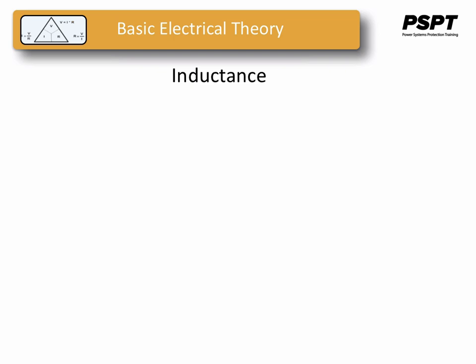Whereas an electric field flux between two conductors allows for an accumulation of free electron charge within those conductors, a magnetic field flux allows for certain inertia to accumulate in the flow of electrons through the conductor producing the field. Inductors are components designed to take advantage of this phenomenon by shaping the length of the conductive wire in the form of a coil. This shape creates a stronger magnetic field than would be produced by a straight wire.